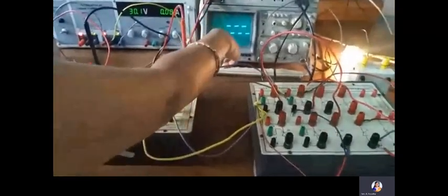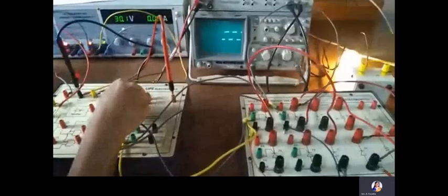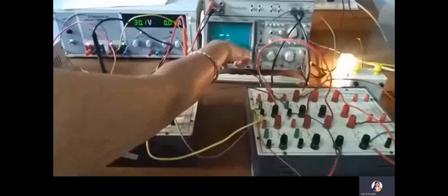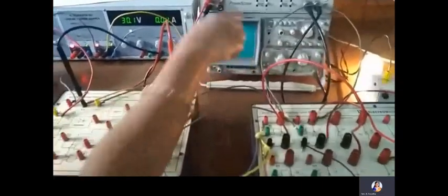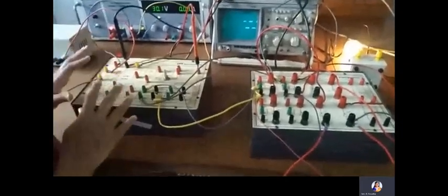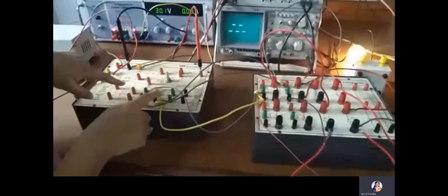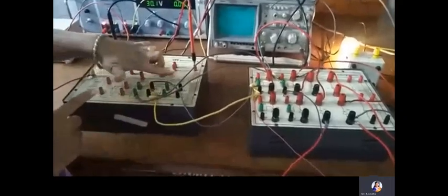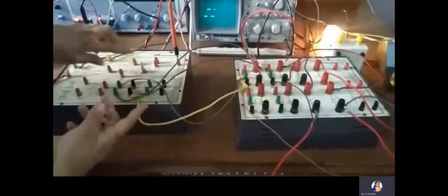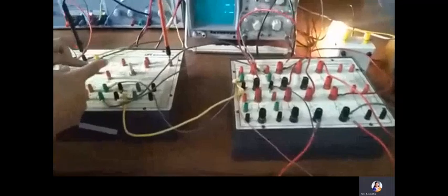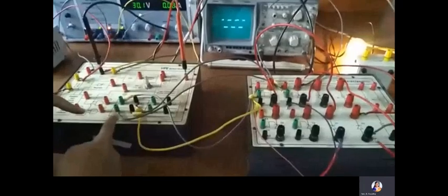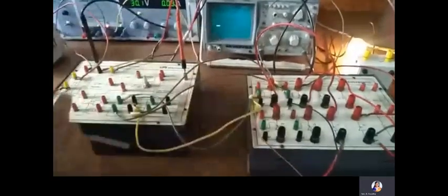This is the reference point. With reference to this, the alpha is 90 degrees right now. Because as I told in the previous videos, one small division is 18 degrees. 18 into 5 gives 90. So this is the firing pulse we have. Now, these generated firing pulses will be available at G1, K1, G2, K2, G3, K3, G4, K4. G1, K1, G2, K2 will be in phase. G3, K3, G4, K4 will be out of phase. So one pulse in the duration 0 to 180 degrees is given to T1. One pulse at the 180 to 360 degree duration is given to T3.